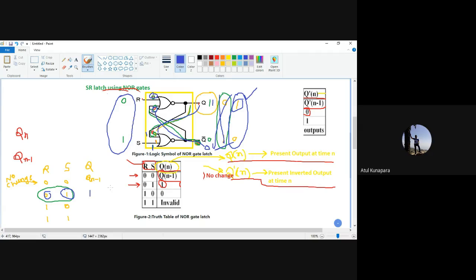Previously, if it was reset, then also it will be made logic 1, and if it was set, then it will be kept as it is. It's not like whenever the set condition is applied, your output state is going to change. No, your output value of Q will change according to the input. If you are giving set input as logic 1, then your output will be made 1 only. If it is already 1, it will remain 1 as it is. No change will come in that.